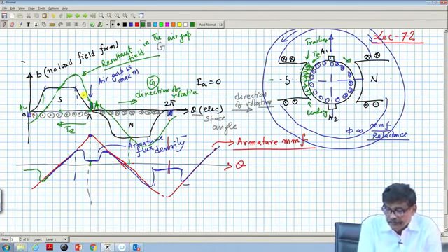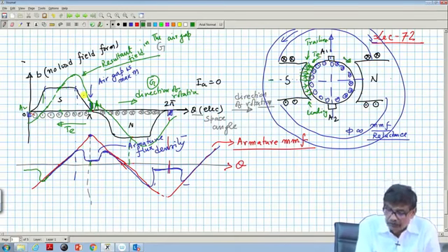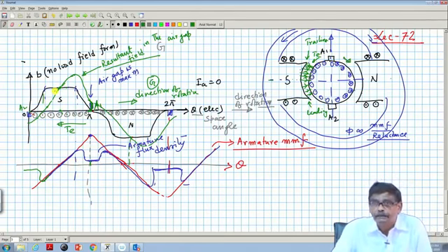But what I am telling, if there is no saturation taking place for some low value of armature current, maybe the increase in flux in one half will be equal to the reduction in flux in the other half, that is this area and this area are same. So, flux per pole will remain same, and we can neglect it, armature after all carrying current has no effect.